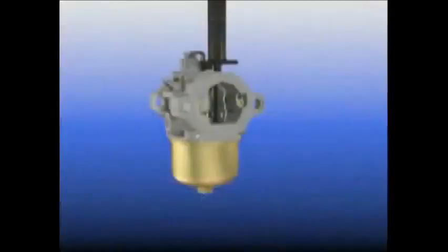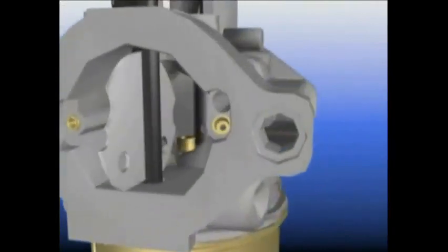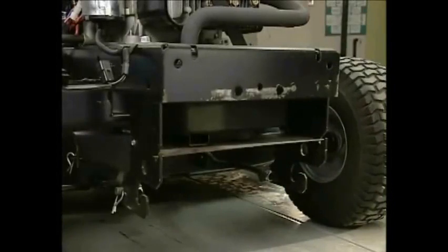When dirt or debris enters the high-speed air circuit, it stops the airflow from reaching the emulsion tube. The carburetor cannot mix the air and fuel when the engine is trying to start or when the engine is under a heavy workload. The visual sign of a clogged high-speed air circuit under load will be black smoke from the exhaust and the possible loss of power.